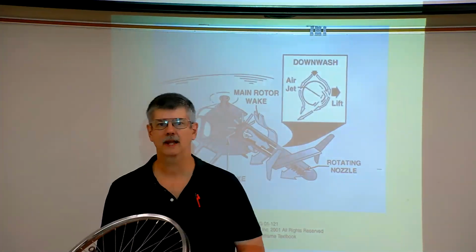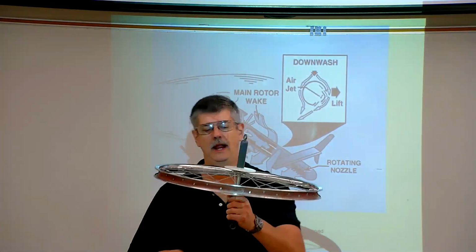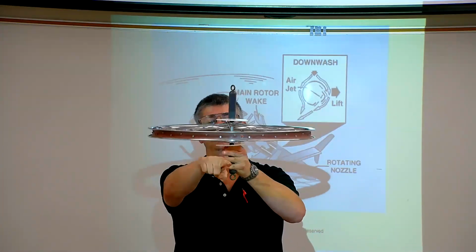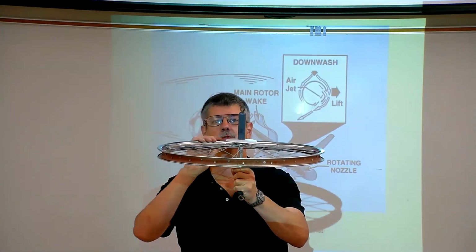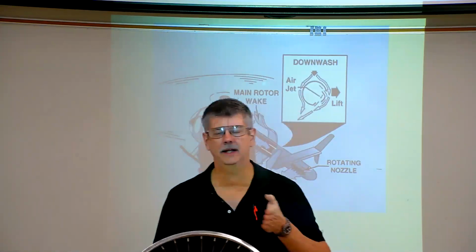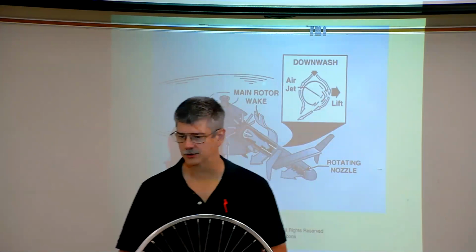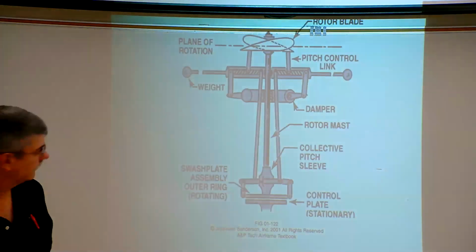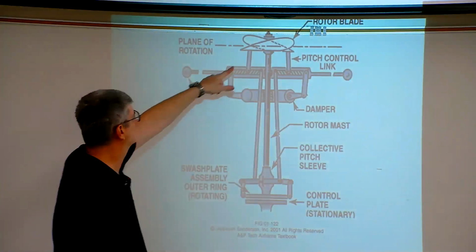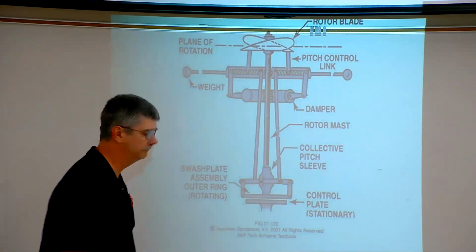So what Bell came up with is a bar that rides underneath the rotor blade. It spins with the rotor blade, but keep in mind, it's perpendicular to the blades, and they're also hinged. So here's the rotor blade, and here is the Bell stabilization bar.